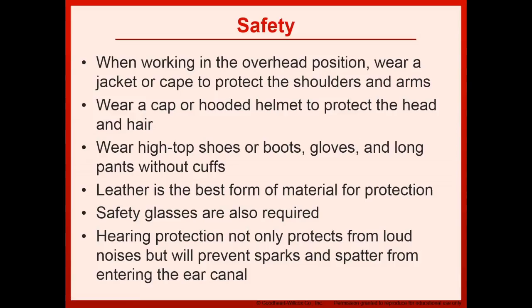Safety. When working in the overhead position, wear a jacket or cape to protect the shoulders and arms. Wear a cap or hooded helmet to protect the head and hair. Wear high-top shoes or boots, gloves, and long pants without cuffs. Leather is the best form of material for protection. Safety glasses are also required. Hearing protection not only protects from loud noises, but will prevent sparks and spatter from entering the ear canal.